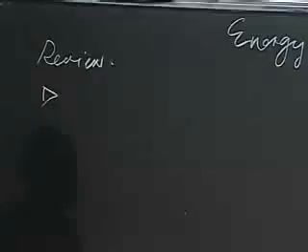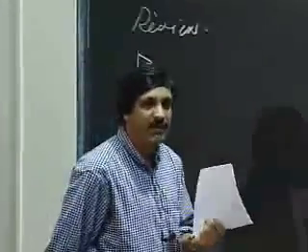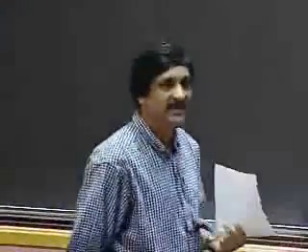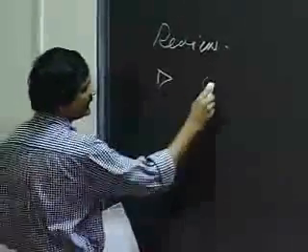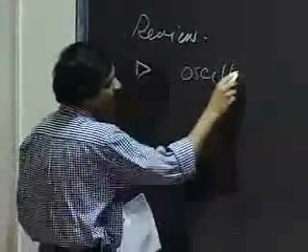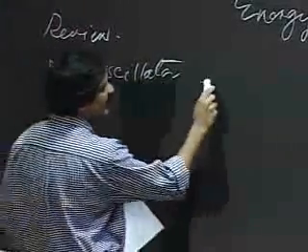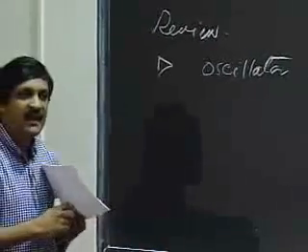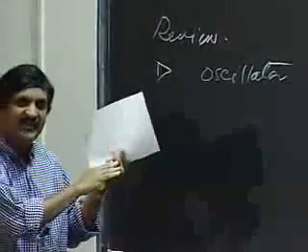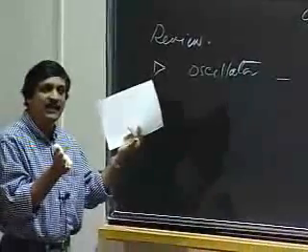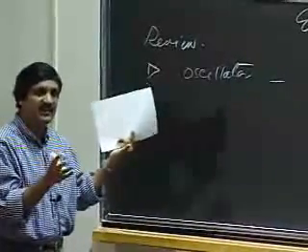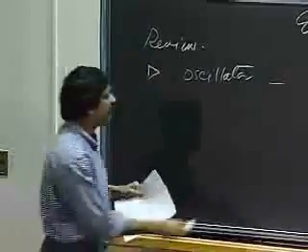We ended last week by looking at positive feedback in analog circuits using an op-amp. In particular, we built an oscillator that allowed us to charge a capacitor, and when the voltage across the capacitor equaled that at the minus terminal, it would flip and keep doing so.